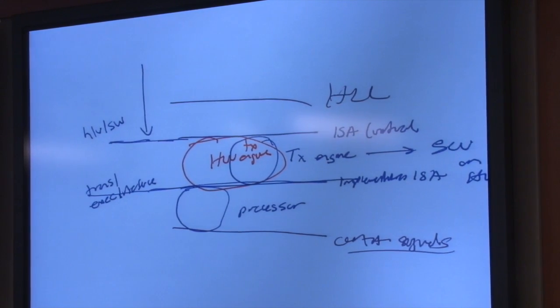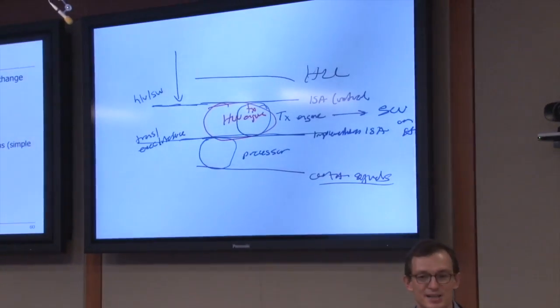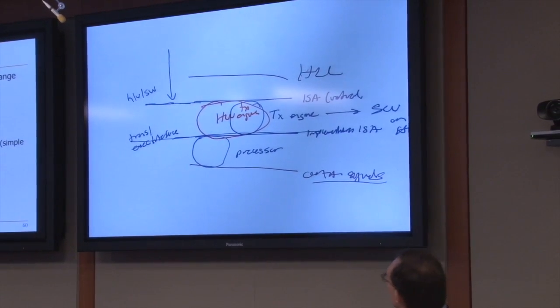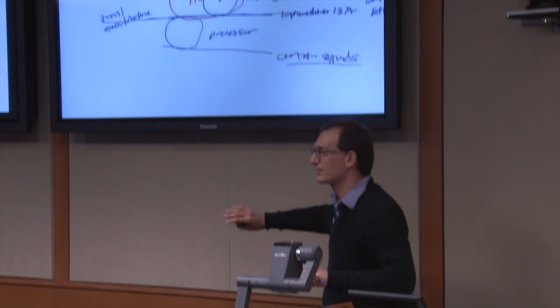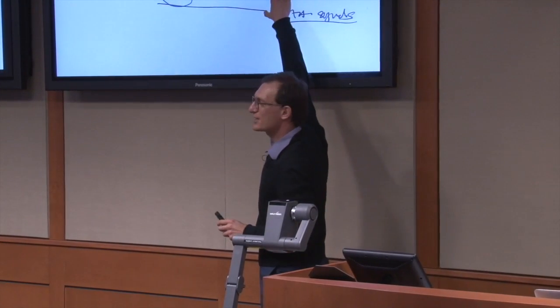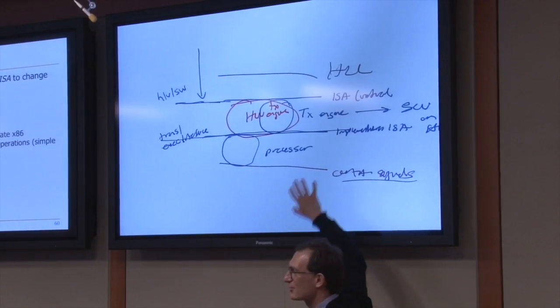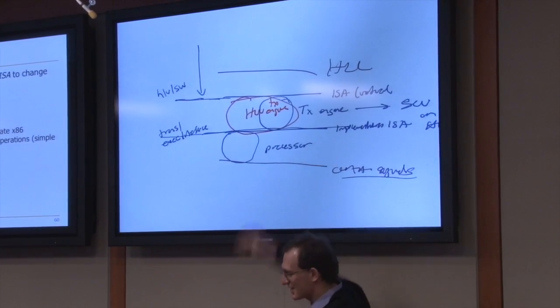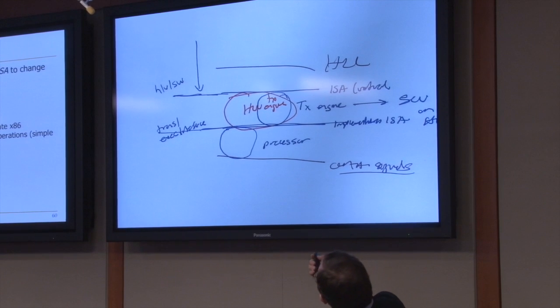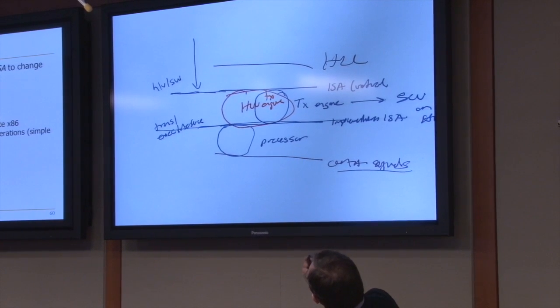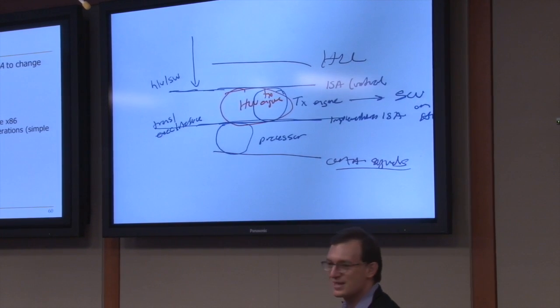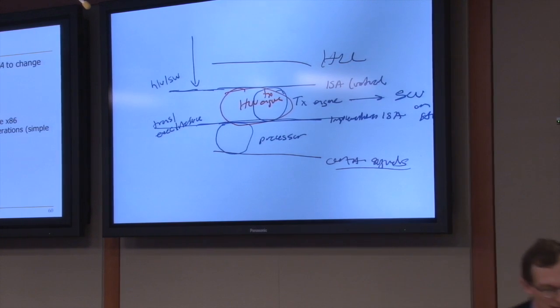It's nice, right? Did you guys know about this? But that's how they made the core of the processor simple. You have this hardware engine that does the translation, and the core of the processor is now simple. It kind of looks like actually a RISC processor. In fact, all of the high-performance processors today underneath look like RISC processors, except the ones that actually have a complex ISA do this translation. They have some additional hardware to do the translation.